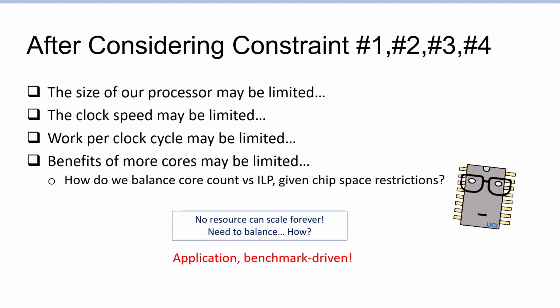And that's part of the reason that, for example, if you benchmark the behavior of desktop class i7, i9 core chips versus the server class Xeon chips, they make different trade-offs between things like cache sizes, number of cores, the amount of ILP exploiting functional units, such as caches and prefetch logic, etc. Different decisions are made for these different lines of processors based on these restrictions and observations about the applications that each chip cares about.